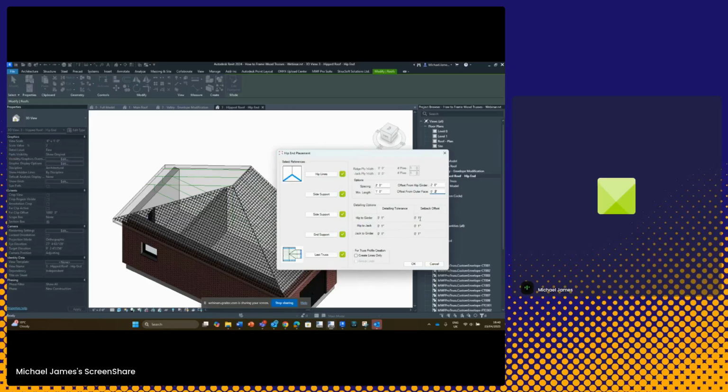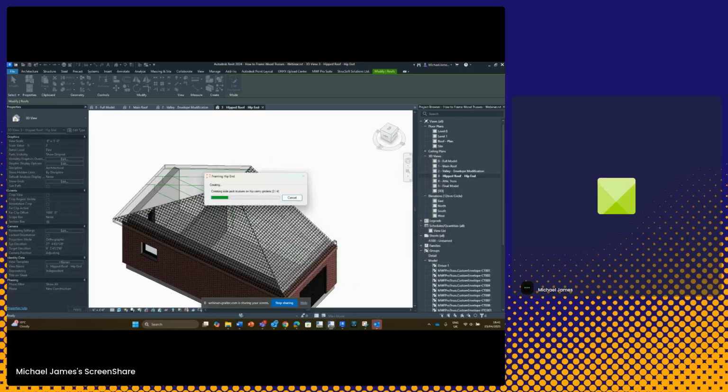And then we have a setback offset, which is in relation to, so we've got the distance from the supporting element, which would be our girder, but then we've got the setback option, which is based on the individual truss members within the truss. So again, with the member thickness being offset from the middle of the model line, the setback offset is in relation to, well, I'll explain once we see it in the model. You'll see it in a moment. So I'll click OK on this one.